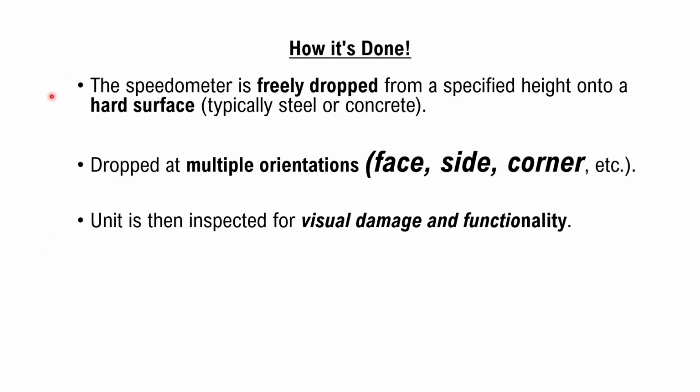In case of this drop test, the speedometer is freely dropped from a specified height onto a hard surface. That could be steel or concrete. It is dropped at multiple orientations, face, side, and corner, etc. The unit is then inspected for visual damage and functionality.